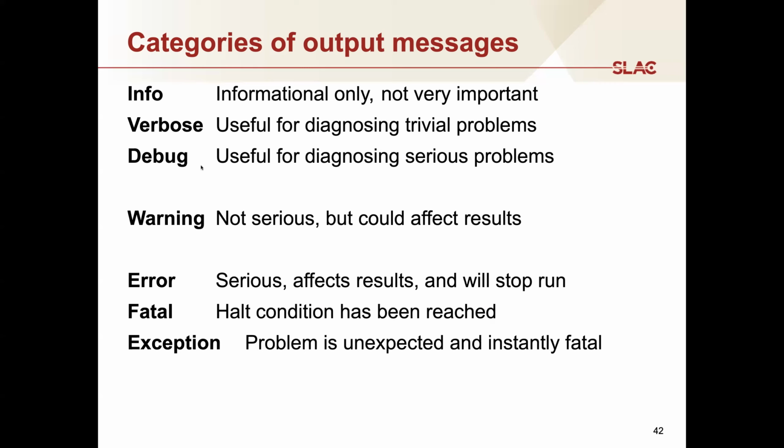Debug is extremely chatty, and it will give you a lot of detail about what the different parts of the system are doing and what they're communicating to each other. And so you'll see things like object such and such advances the clock to this time, and this object doesn't need to advance the clock. This object goes to this state. So there's a lot of information that can help you diagnose more serious problems about what's going on.